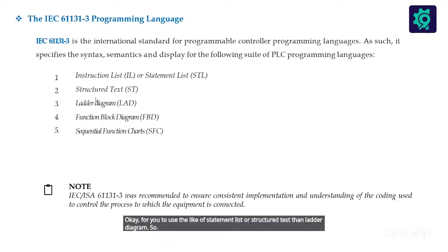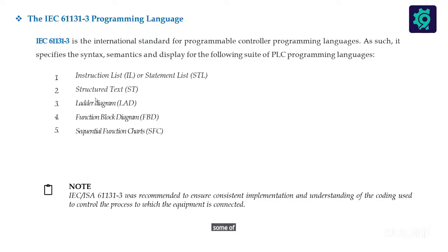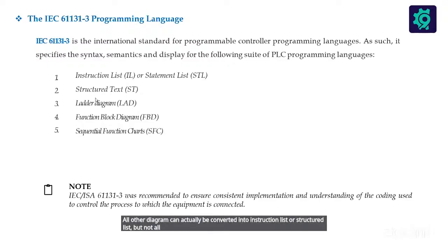So as you proceed in your journey in PLC programming, you tend to see where some of these languages will be more preferable over ladder diagram. All ladder diagram can actually be converted into instruction list or structured text, but not all structured text or instruction list can be converted into ladder diagram. So you have to put that in mind.